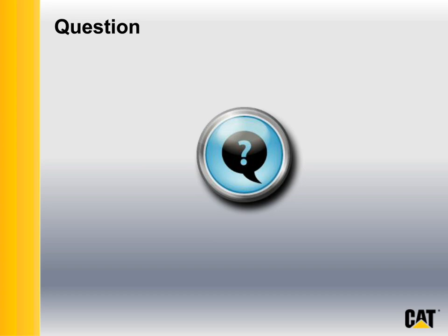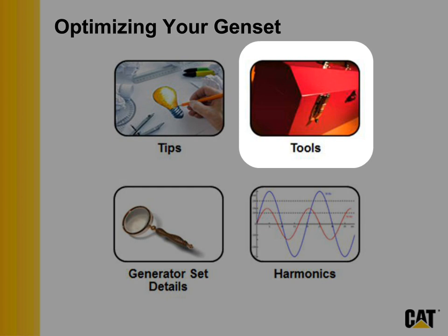I would say if you don't have to adhere to a specification and it doesn't require X number of steps and such sequence, run the optimizer, run it as optimum step selection, and see what is the smallest genset kW/kVA rating. That's the way to determine the optimal number of steps. Again, I think the optimizer is just a fantastic opportunity for anybody that has to do a genset sizing.